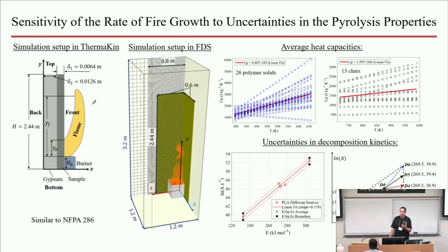Now, in the process of doing that, when you analyze these properties with these experiments, you have to create a sample with a good thermal contact, which means you cannot put leaves in your TGA, right? You have to destroy the sample to some degree. Now, you can do interesting things with that, and people have done that already. Like you can try to cut out little representative chunks of actual materials and see how that impacts the results and all of that. But ultimately, in the TGA and DSC type of experiments, you want material that has uniform temperature that you can control. And that puts certain limitations on what you can do with the samples.